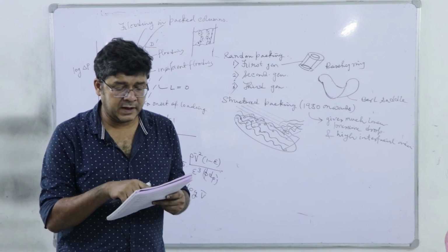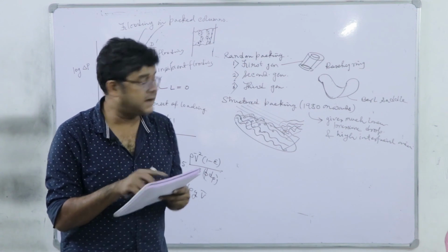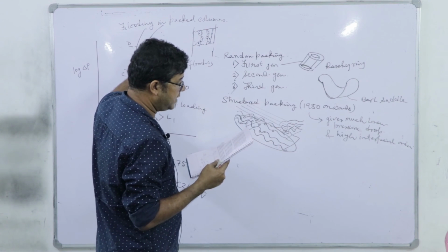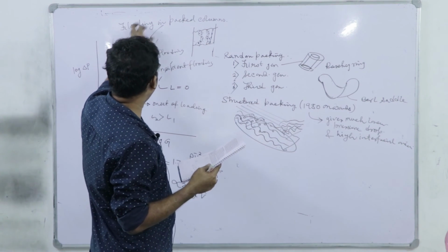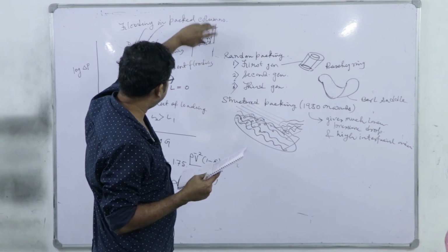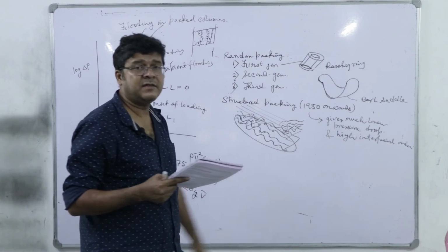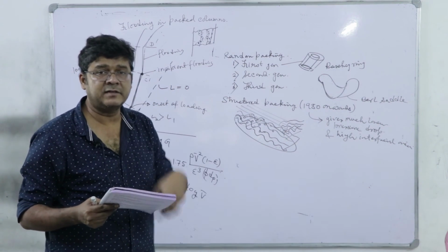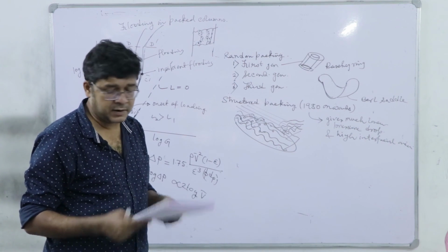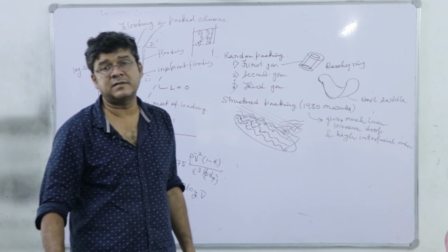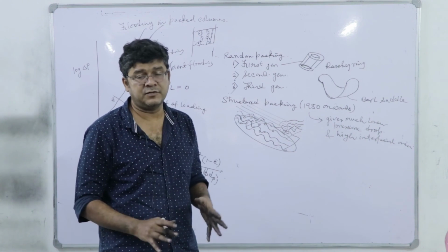So, the phenomenon is flooding, and the bed becomes flooded at this point D, right, and the void in the bed becomes full of liquid. From here we have a paradigm shift of the continuous and dispersed phase. Now the liquid becomes continuous, the gas becomes dispersed, and as a consequence the mass transfer efficiency tremendously drops.